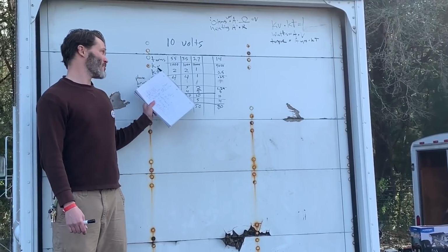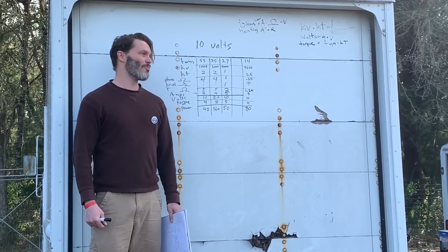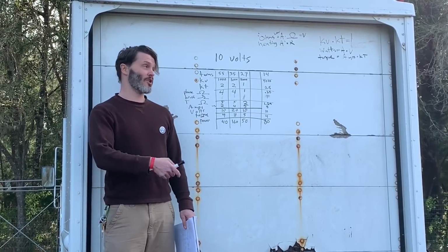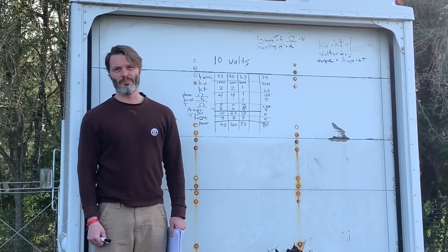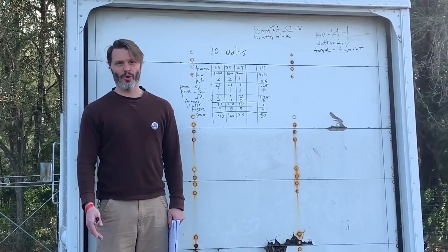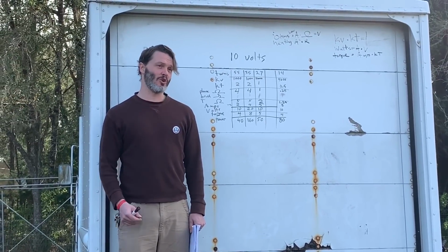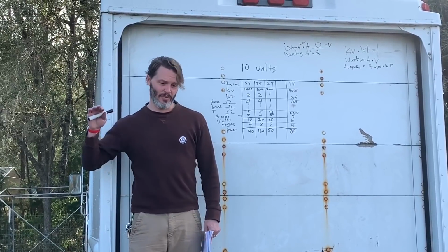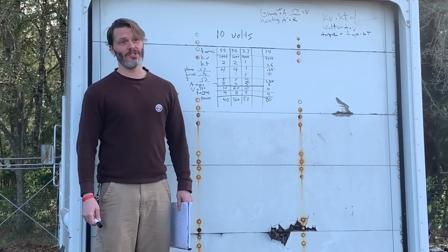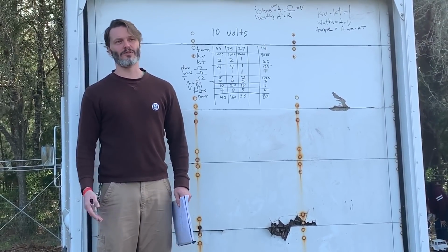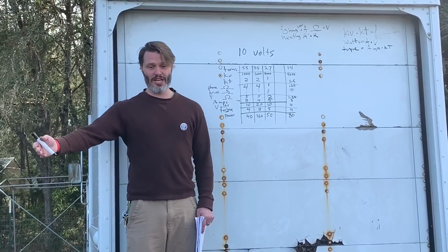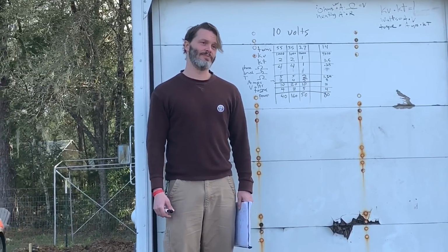Yeah. And if we go to a much faster motor, they become punchier and punchier, and that gets into the inductance of the motors, because the inductance also ends up getting cut in quarter along with the resistance, and it ends up being almost an uncontrollable system. So if anybody's in the racing scene, you get a motor that's like a 3.5 or a 4.5. It gets so punchy that you can't control it, so you end up either turning down your throttle, or you add a little bit of throttle ramp time depending on the controller, so you can actually control it and still have that wheel speed on the back end that you want. So, always a fine balance. A little bit different for crawlers versus racers, but there's always that concession that has to be made. One thing about motors is you have one thing that changes, and it's going to change something else along with it. It's always a balance.